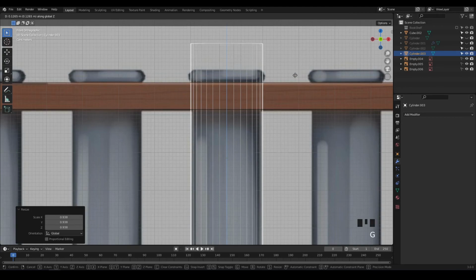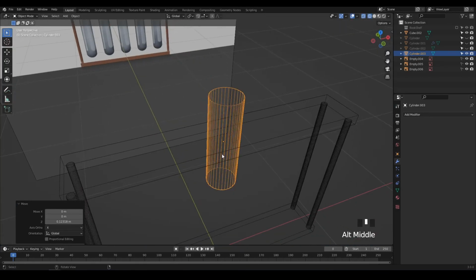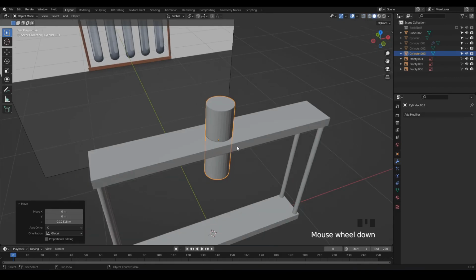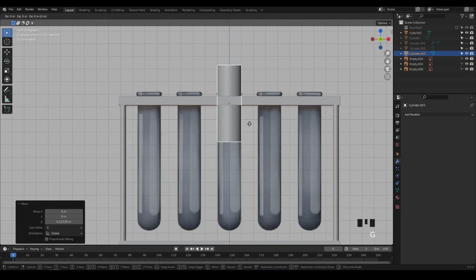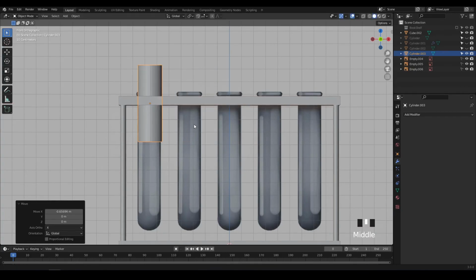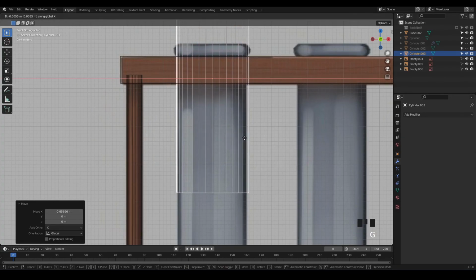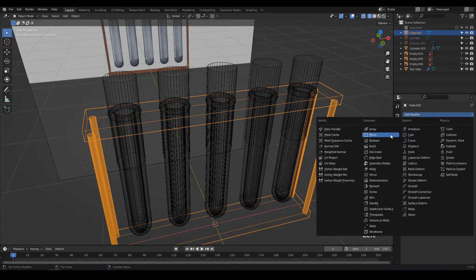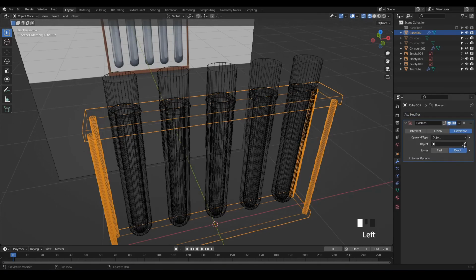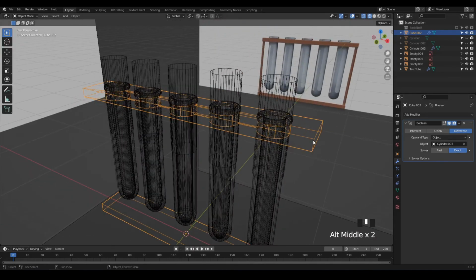This looks okay. I'm gonna set it here because I want the hole to be in here at the top, and I can do exactly what I did with the test tube, meaning setting this in here, and now I can go to this object, add a Boolean modifier, select these cylinders and the difference option.